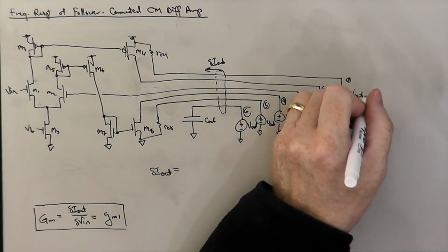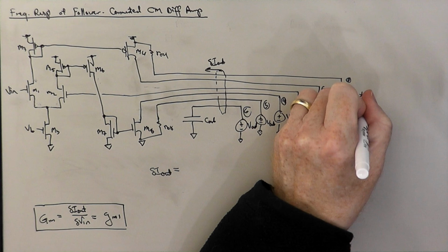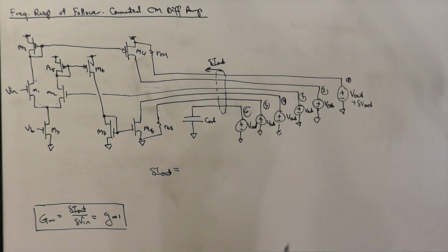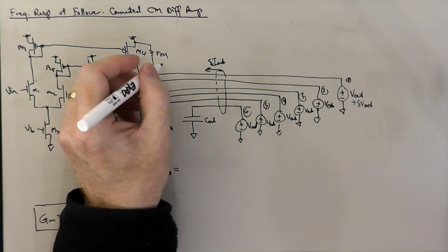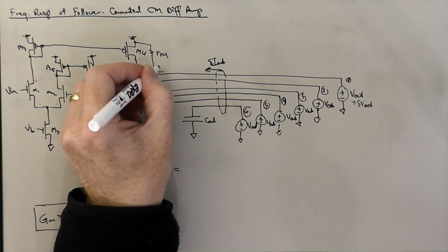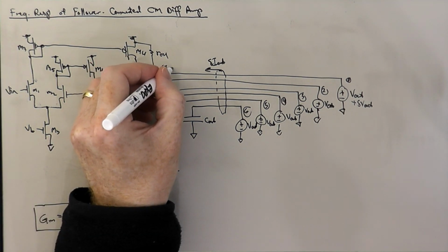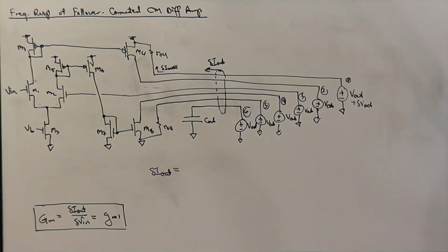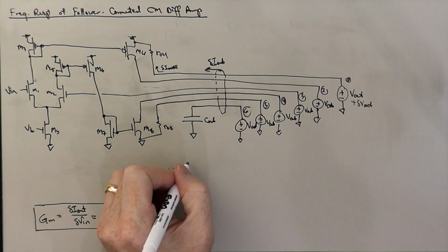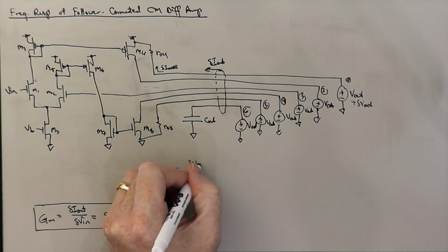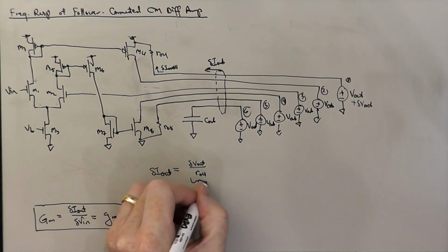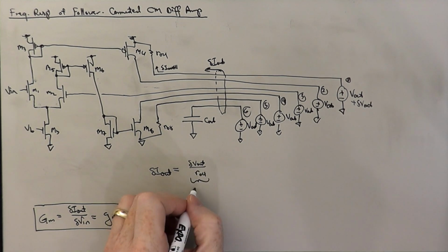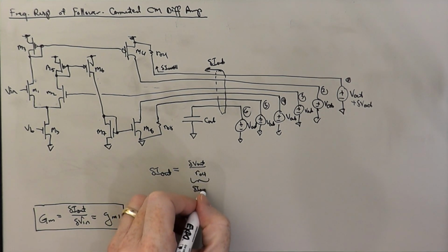So let's start out with our delta V out here on branch 1. What are we talking to here? Well, we have an early effect resistor, and we're going to have a delta I out 1, 1. And that is going to be simple enough. It's going to be given by delta V out over RO4, which is incremental Ohm's law. And that's delta I out 1, 1.